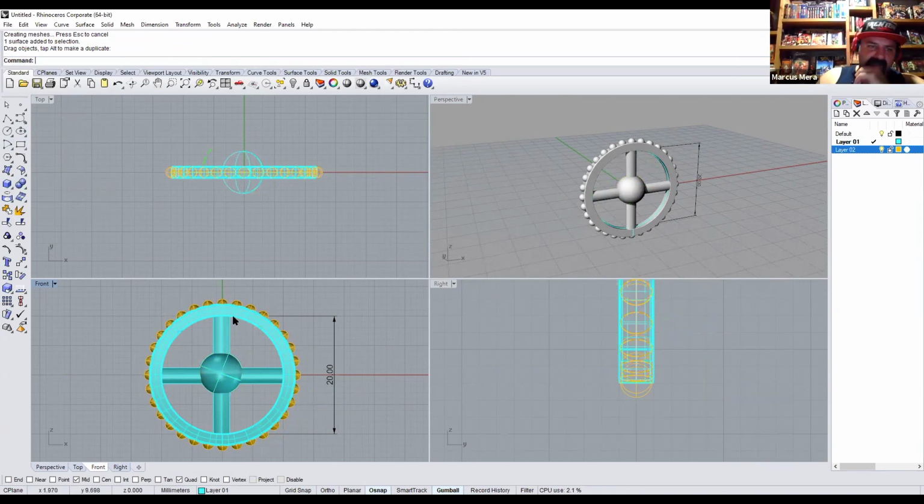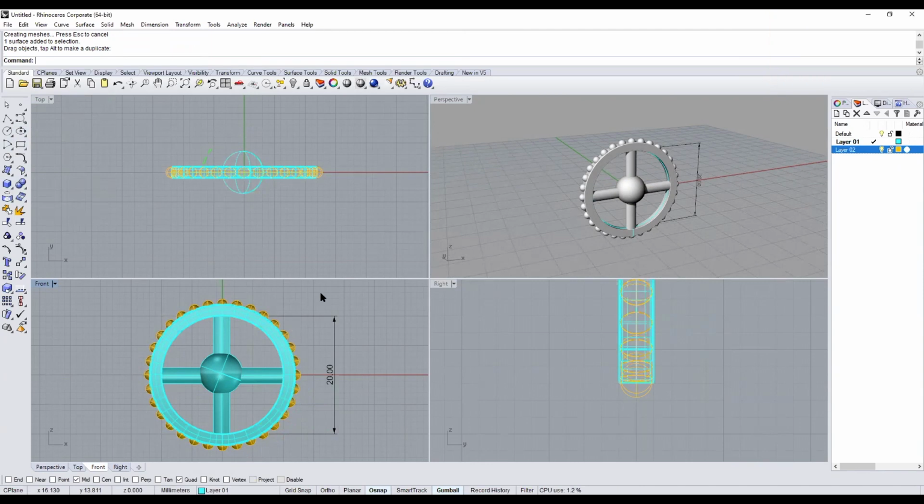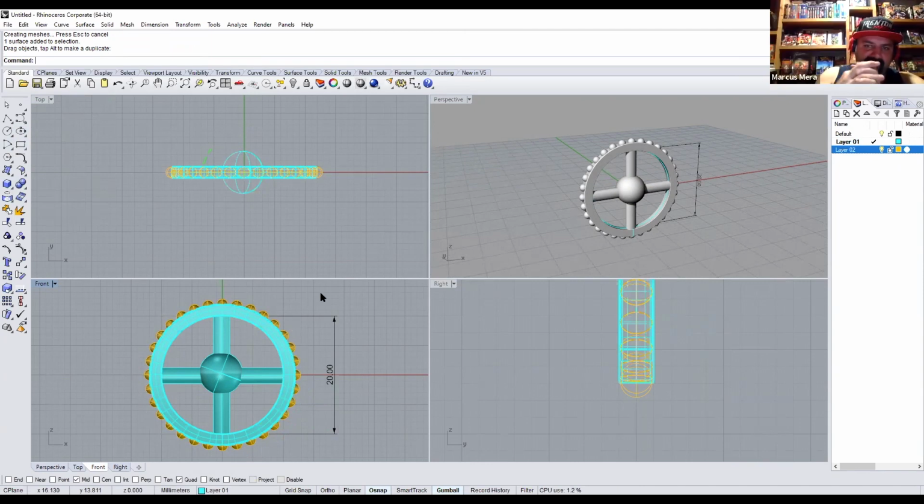Yeah. And then when you're done, you just cut here, here. Keep the metal, return the metal, whatever you want to do. But that way your design is perfect from the casting and you have plenty of metal flowing. You always have porosity with casting, but you have much nicer, cleaner castings.